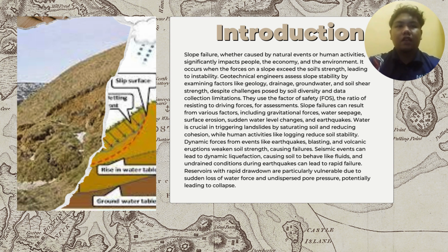Seismic events can lead to dynamic liquefaction, causing soil to behave like fluid, and undrained conditions during earthquakes can lead to rapid failure. Reservoirs with rapid drawdown are particularly vulnerable due to sudden loss of water force and undissipated pore pressure, potentially leading to collapse.